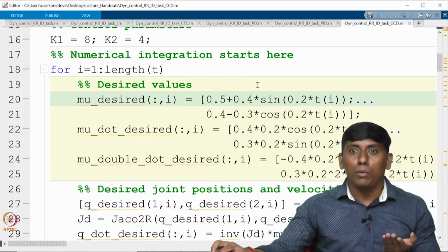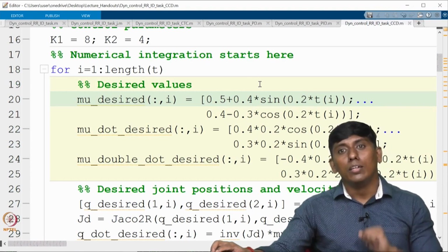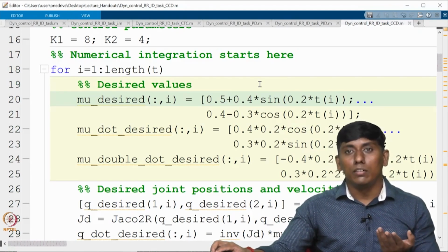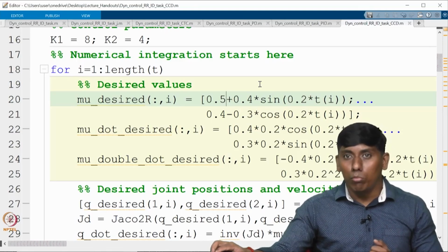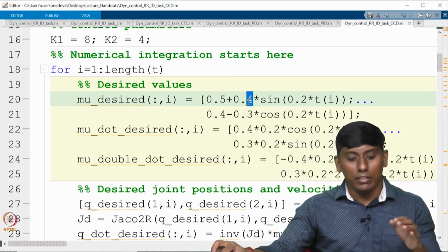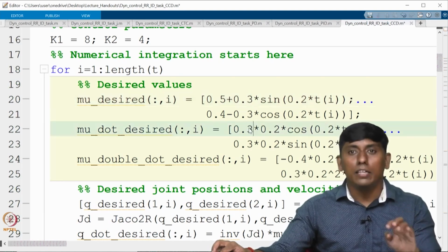The other one is not possible in task space. The other one ends up with what you call the boundary singularity. In the sense the Jacobian would be a singular one, so this is also not possible. So now you have got why it is not working. You have the idea, right?